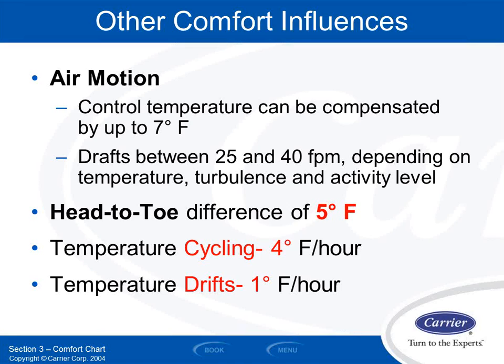And that rule is for overhead heating systems: you can have a discharge air temperature coming out of the diffuser of no more than 15 degrees above whatever the space temperature is. Otherwise, you're not going to get proper mixing in the space. And the purpose of the diffuser is to get mixed air. That's its job in life.